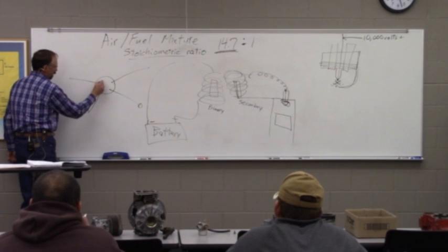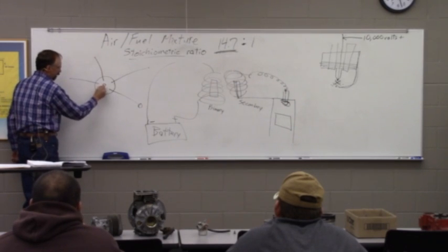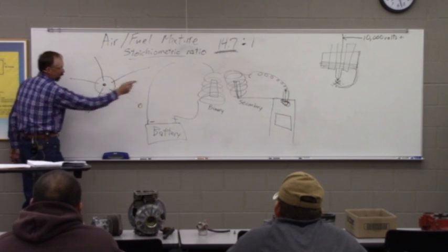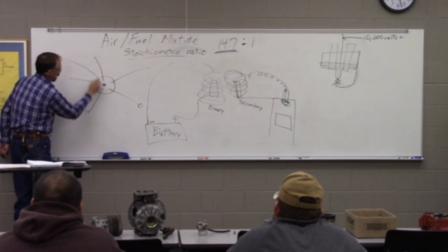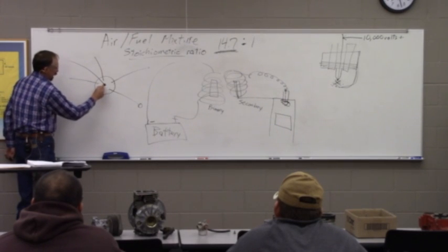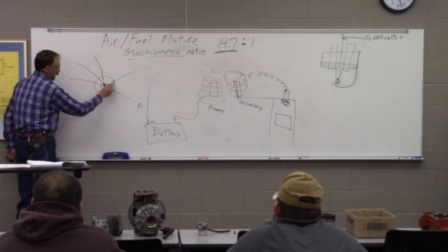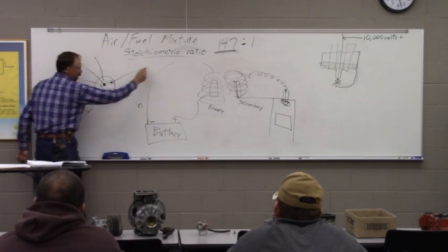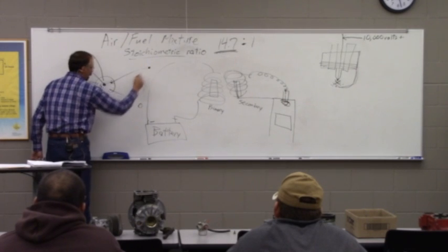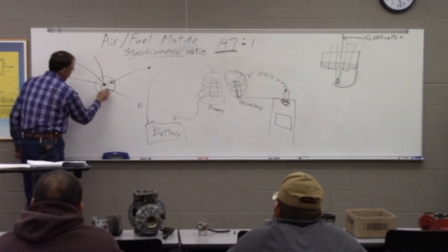And there was a rotating shaft in the middle of it, and we would have the wire from this coil that makes our spark coming in here to the middle of it, and then there was a rotor, it's called, that would point like this, and it had a contact that connected this contact and this contact when we wanted this cylinder to fire. And then it rotated.